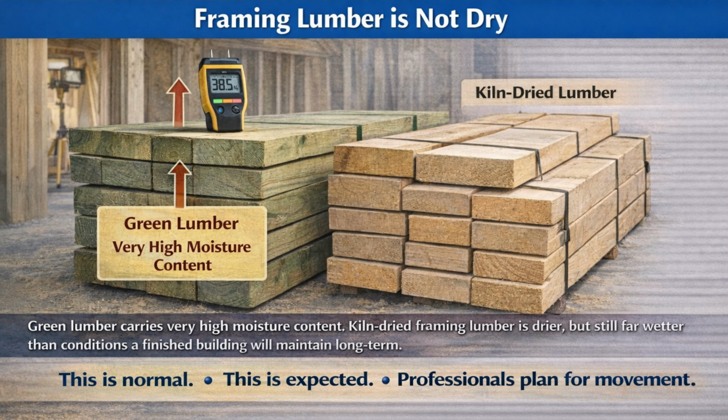Framing lumber does not arrive dry. Green lumber carries very high moisture content. Kiln-dried framing lumber is drier, but still far wetter than the conditions a finished building will maintain long-term. This is normal. This is expected. And this is why professionals plan for movement instead of denying it. Understanding moisture content turns wood from a mystery into a predictable material.